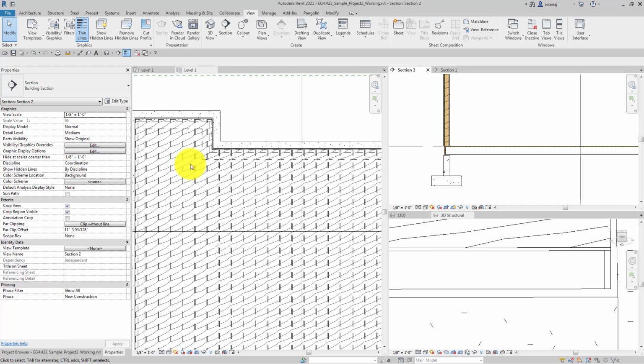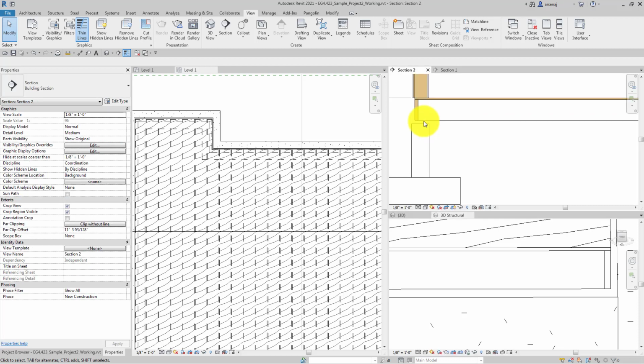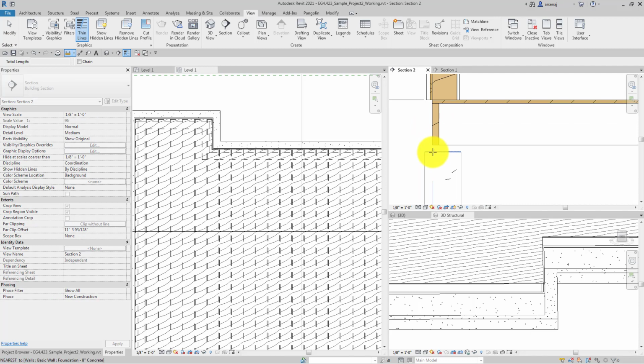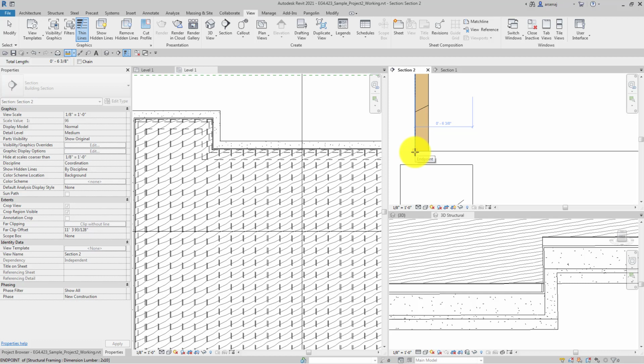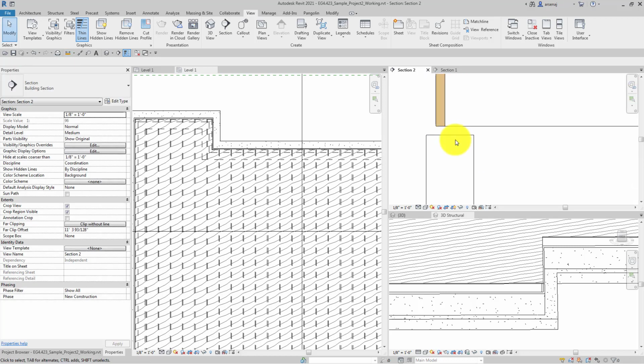So now we're almost done. Actually, we've got our foundation wall, our footing, our header joist that's going to make up the perimeter, and so all we need now is this sill plate. For the sill plate, I'm going to use, looks like we have about 6 3/8 from the inside of the footing to the face of this. So we may want to use a 2x6 flat stud.